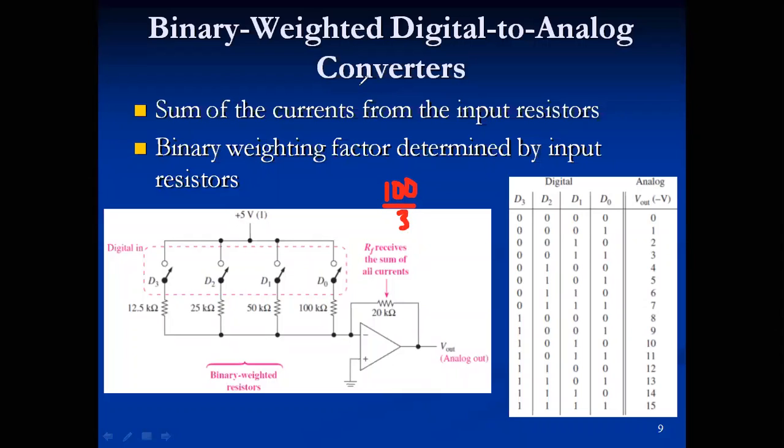And just a little shortcut for you guys. If you go on to do circuits, when you have parallel branches that are multiples of each other, you can do this. 50 is the same as 200 ohm parallel branches, and so whenever you have the same value in parallel branches, you just divide the resistor value by the number of branches.